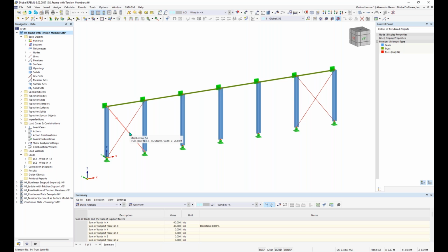And these members are bracing this frame. There are lateral bracing in the X direction. And we're also just assuming this frame has been taken from another structure. So imagine the top here is framing into a roof. And so these supports are just supporting it in plane and out of plane. And so this wall would need bracing in the global X direction, like I just mentioned, and that's what our X bracing here is. And you can see this X bracing, if I double click on it,